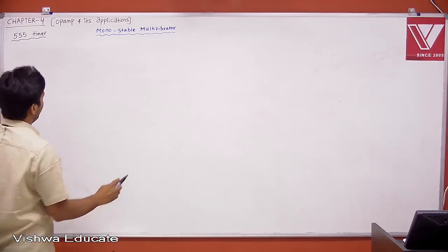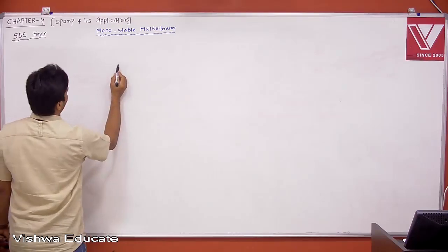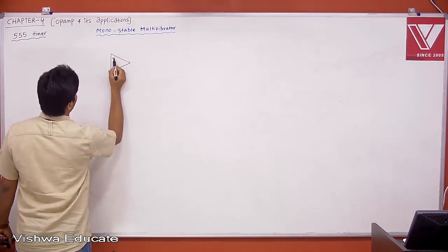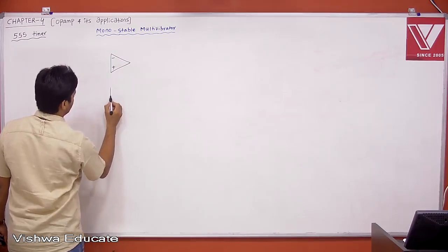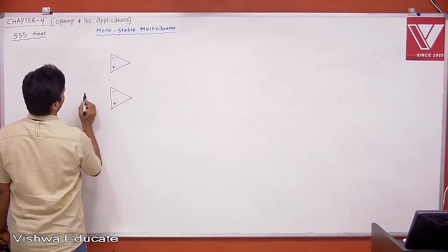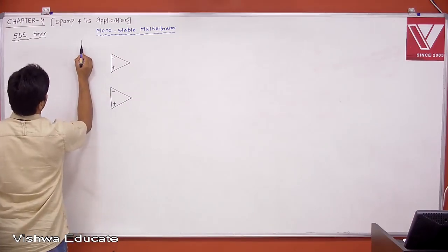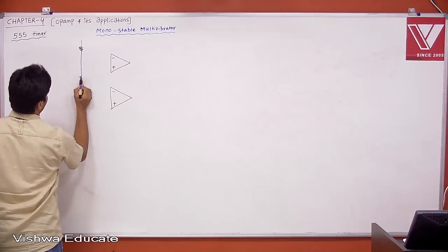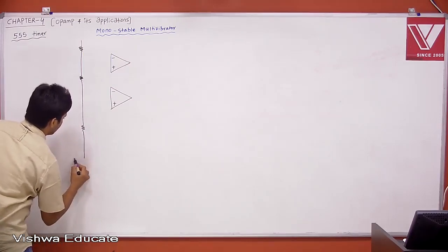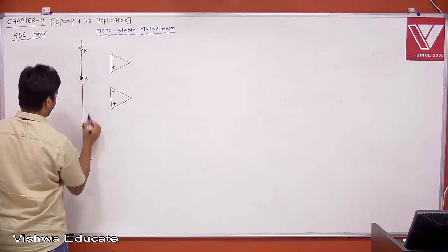Again we have two op amps, acting as comparators. Okay, now we have two op amps, minus, plus, minus, plus. Now we have a resistor chain, this is ground, this is the reference generator which is there inside your 555 timer.